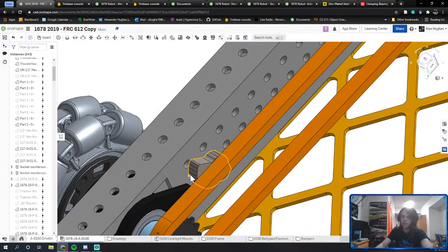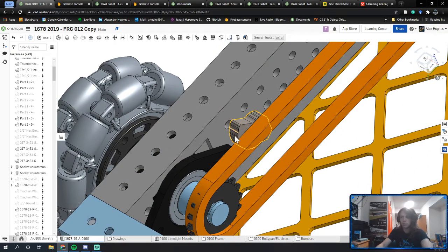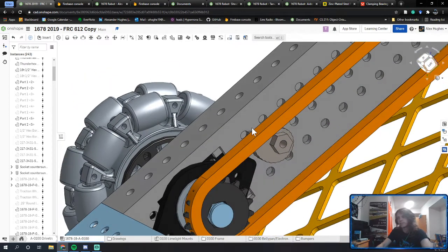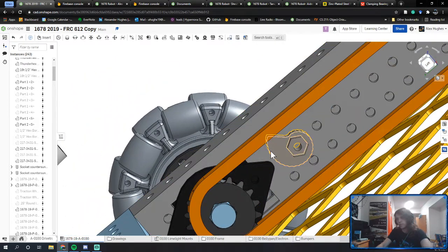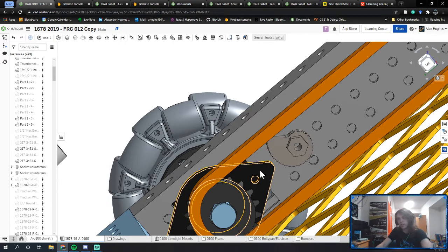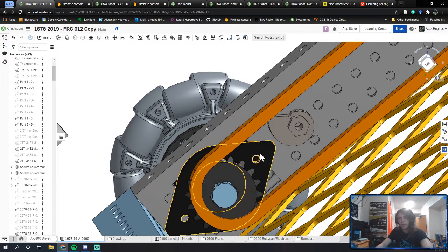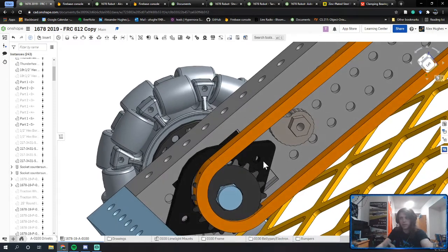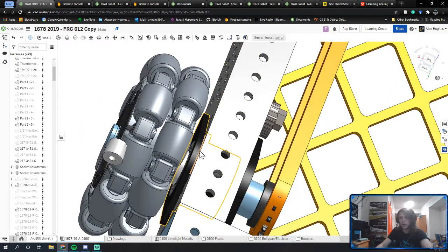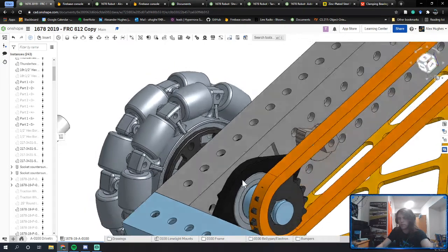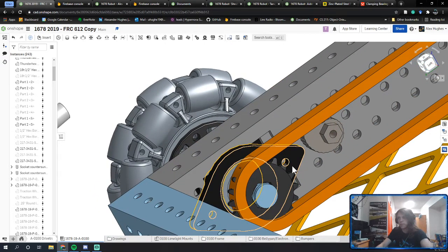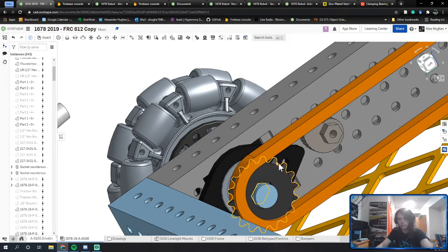And so what a cam does is, as it twists around, you can notice this seashell type shape to it. If you think about twisting the cam counterclockwise, the end of the cam is eventually going to push and touch the bearing block here. The bearing block is, for the most part, free floating. It's clamped to the other side of the bearing block, and it touches the bottom of the rectangle we cut out. But there's nothing preventing it from sliding left or right.